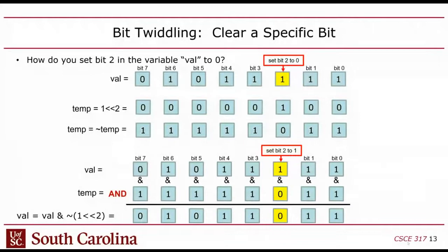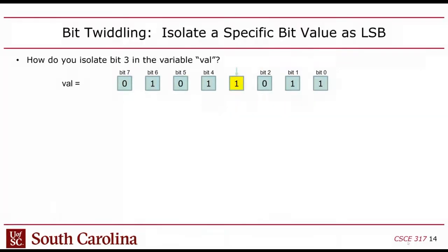And that's important when you're doing programmed I/O, because you oftentimes have to restrict whatever you're doing to specific bits. You don't want to wipe the whole register out. You don't want to have side effects and change bits that you don't intend to change. So this isn't me just being anal about this. This is critical. If you change bits that you don't mean to change, things will break.